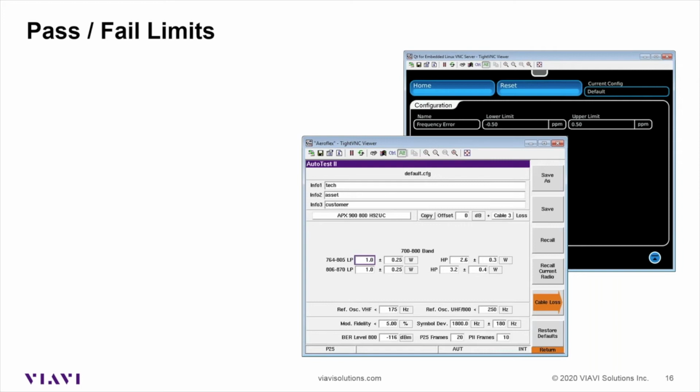The other thing that I was going to show was some interference that was kind of intermittent. I've had customers that have multiple benches in the shop. One technician's over here testing his radios manually, we've got auto test running over here, and just when that other technician would key up his radio, it would cause failure. So it was intermittent, but it was always the same frequency. So that's something to be aware of.